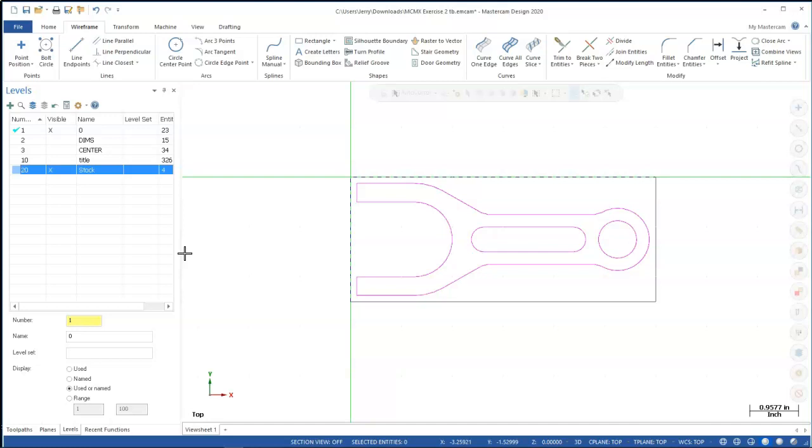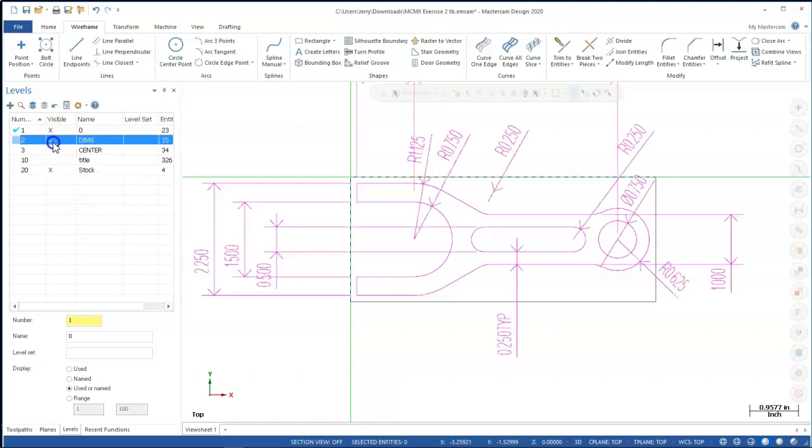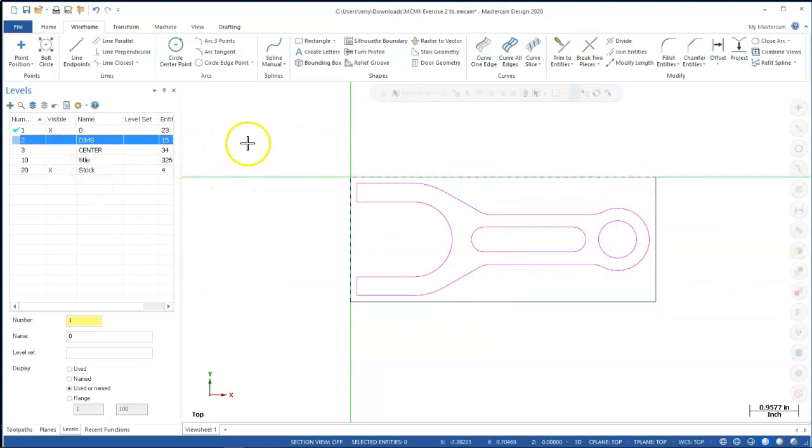The easier way would have been just to say delete everything outside of this box: the title blocks, the dimensions, everything goes away. But on the off chance that I want to go back and check it, or reference this document, I can still pull that up and have that information available. Let's just check a dim real quick, and that is 0.75. So I ought to be able to get a 1/2 inch end mill in there and not be in any kind of collision. And then when I'm through, okay, we're done.